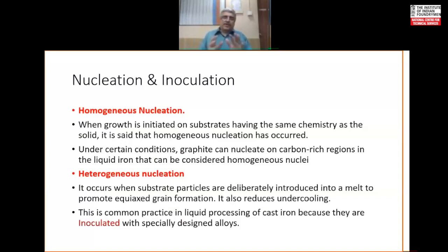So this is a common practice in liquid processing of cast iron, because they are inoculated with specially designed alloys. So heterogeneous nucleation is called inoculation.